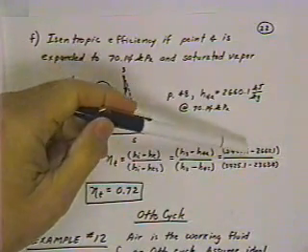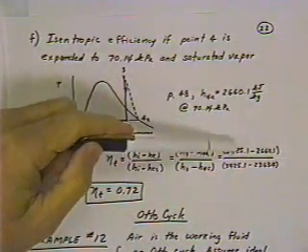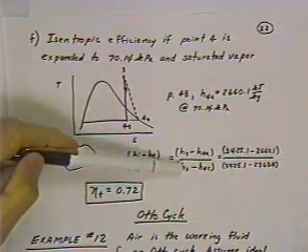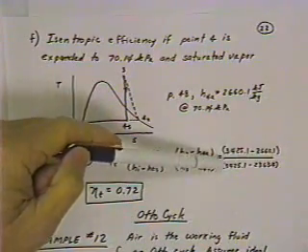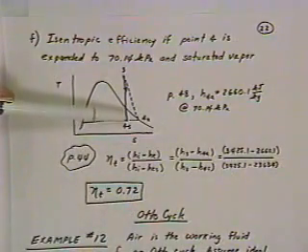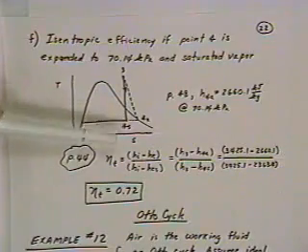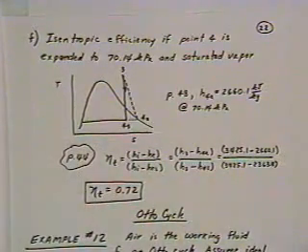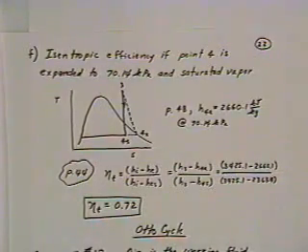H3 is 3425.1, our state entering the turbine, and the theoretical change, H3 minus H4s, is the 3425 minus the 2363.4 that we calculated as the isentropic expansion through this particular condition. So if we do that, we get an efficiency of 0.72, which gives us the isentropic efficiency for the turbine.